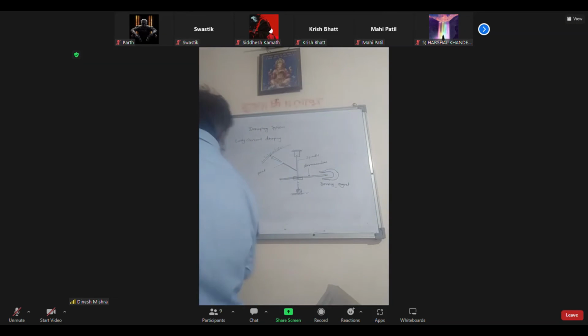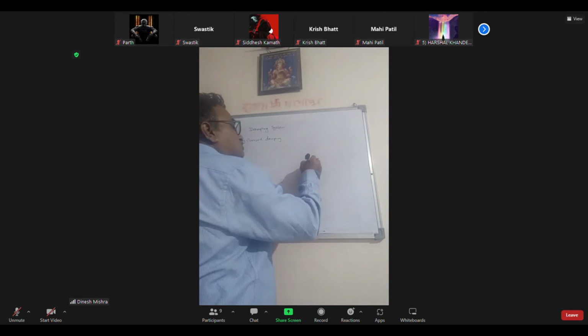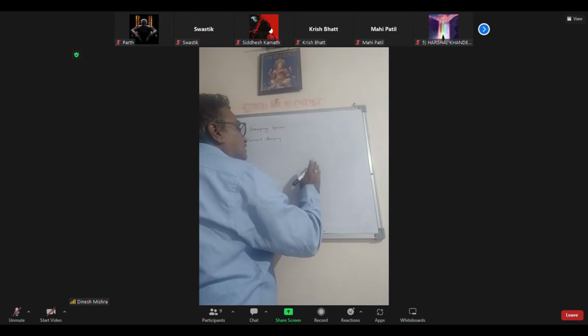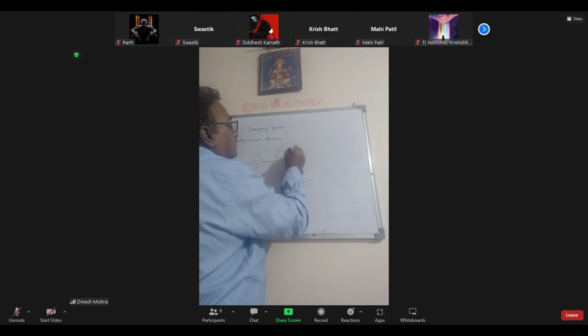See that, one more thing. आपने practical किया है ना अभी? So, measurement of current, measurement of voltage, सब पता है सर ने? When you are measuring the current, the ammeter is connected in series. For measuring voltage, you use the voltmeter. Suppose this load is there. A load है. Many kinds of load. So this is your supply, this switch is there. So I connect the ammeter here, and that will again go to the load.